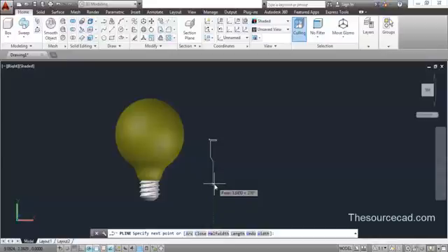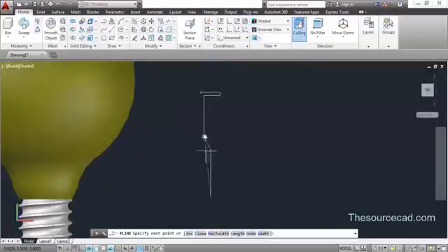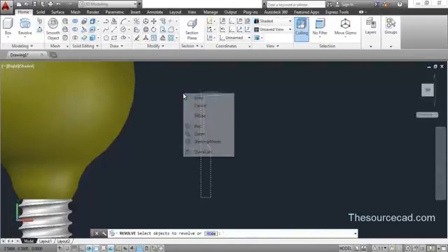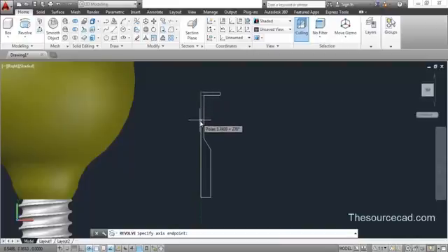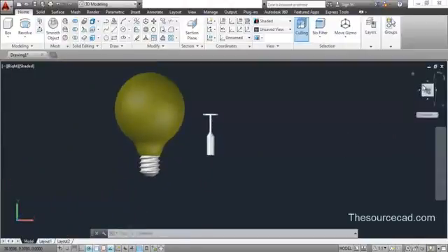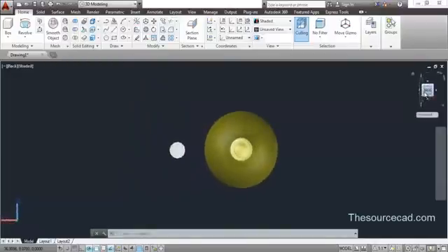Okay, let's click here. This seems okay. Now let's drag that point, and okay, so here we have a complete closed loop. Now go to sweep revolve tool, and now let's go to revolve, select this profile, enter, and click on any 2 points on this line, and press enter. Okay, so here we have this profile. You can see it clearly here.